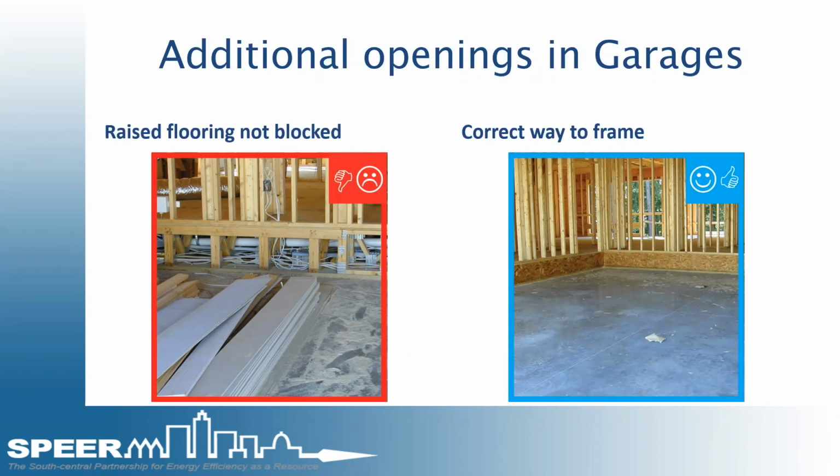Code doesn't spell it out the way Energy Star does, but garage is considered an unconditioned space by code. Energy Star sees it as a contaminant source. So code's starting to come around to that same thing, saying it's pollutants, it's contaminants. You need to air seal the house and be separated from the garage. The more resiliency and sustainability get pushed into objectives, that's becoming more the leading cause than just air. But Energy Star also says contaminants cannot breathe their way into the home.